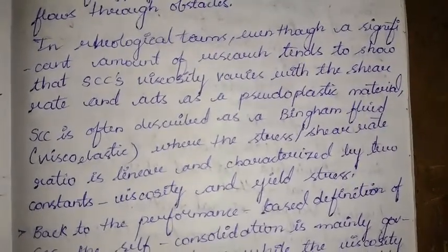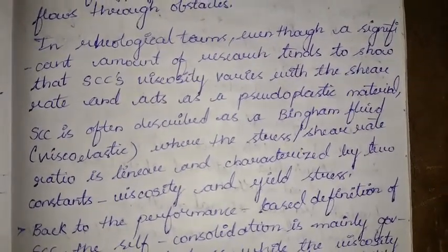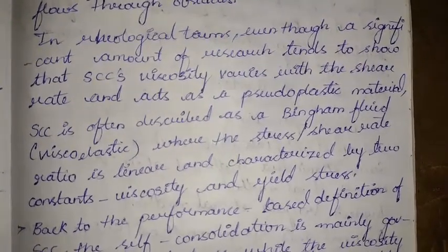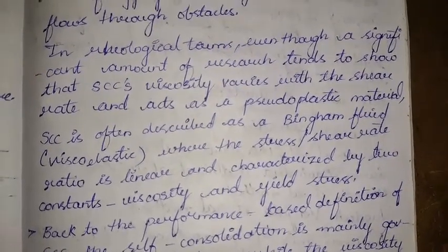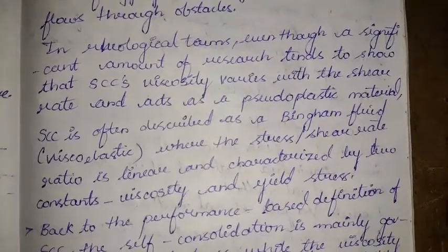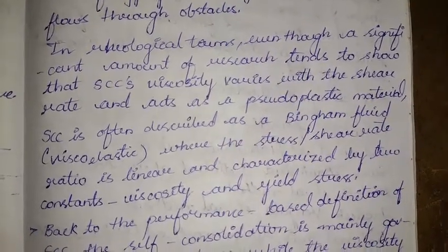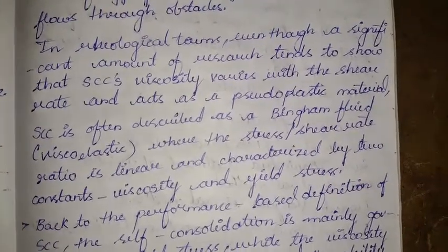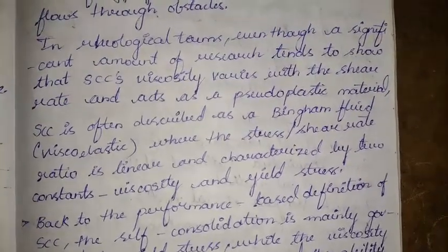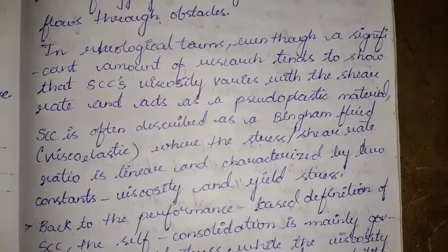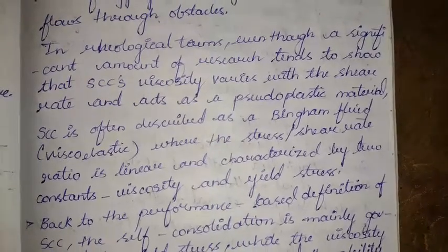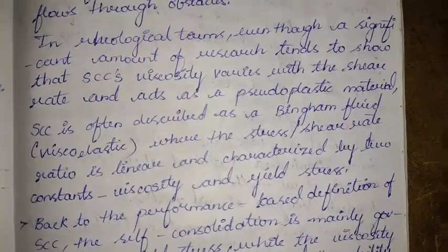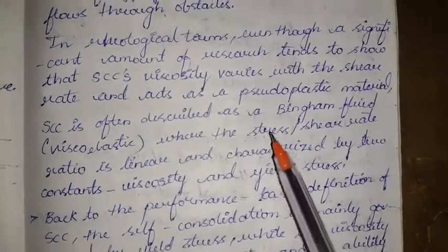In rheological terms, even though a significant amount of research tends to show that the self-compacting concrete's viscosity varies with the shear rate and acts as a pseudoplastic material, self-compacting concrete is often described as a Bingham fluid, where the stress to the shear rate ratio is linear and characterized by two constants, that is viscosity and yield stress.